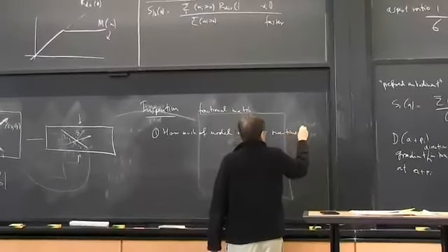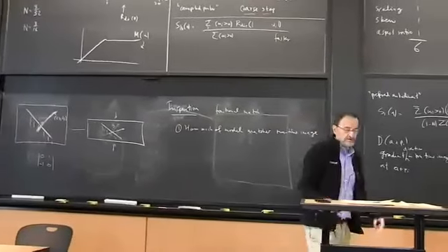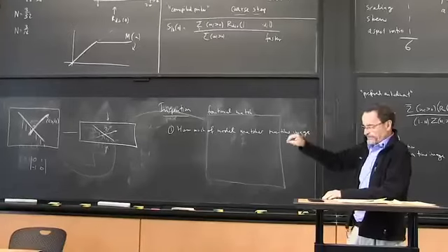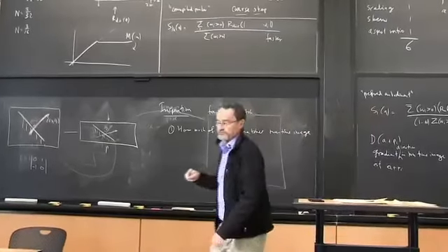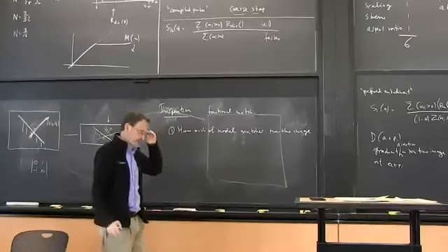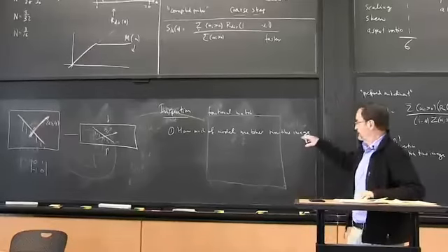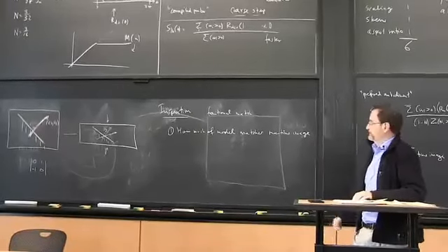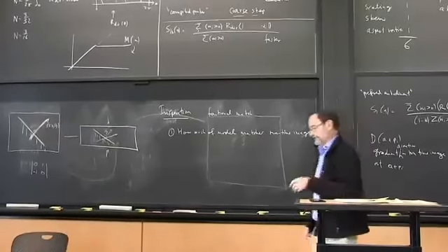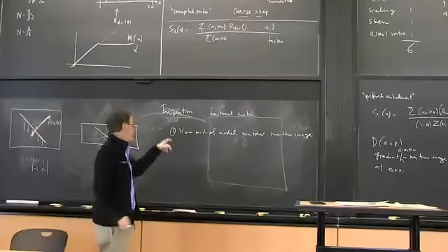Runtime image. Okay, so the model consists of probes. We put the probes down on the image, and for each place we can determine whether it's a reasonable match or not, and in the process we can calculate a percentage. And if the object is partly obscured, then that fraction will be lower. If say you're looking at a gear and some of its teeth are missing, then you'll get a match, but the score won't be 1. And so that's one direction.